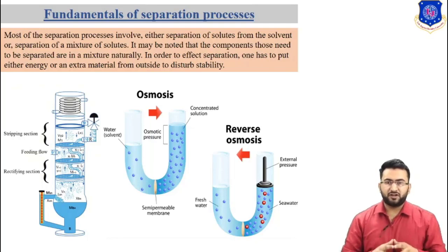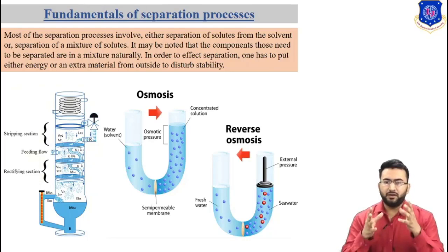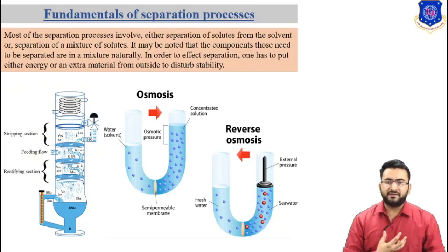In most chemical engineering systems, separation processes are an integral part of the entire process flow sheet. If we consider a reactive system where certain products are of primary interest, separation units are put either upstream or downstream. In such a system, a reactor is the heart of the system. It may happen that reactants are gaseous and should be devoid of moisture. In such a case, a separation unit must be present upstream. On the other hand, if a particular product is kept in mind, a separation unit must be placed downstream of